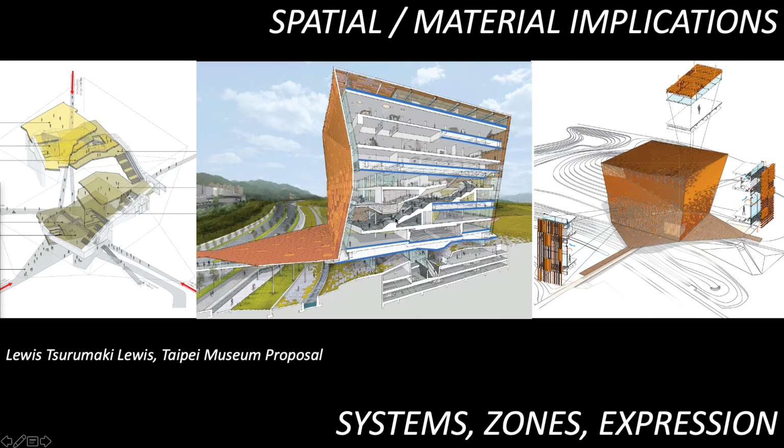But I also like this because we have combinations of spaces that are really set aside for services. This is this part that we're going to call the floor pack. So this area that in poche appears hollow, but in reality is full of all kinds of things. Ductwork, plumbing, electrical devices, everything fits up in this floor pack. And so I really like here that they have identified zones where that floor pack is very active and very full, and then other zones where we have high degrees of openness. And it is not necessary, because these floor packs are doing jobs on a regular interval, to have these closed chambers everywhere.